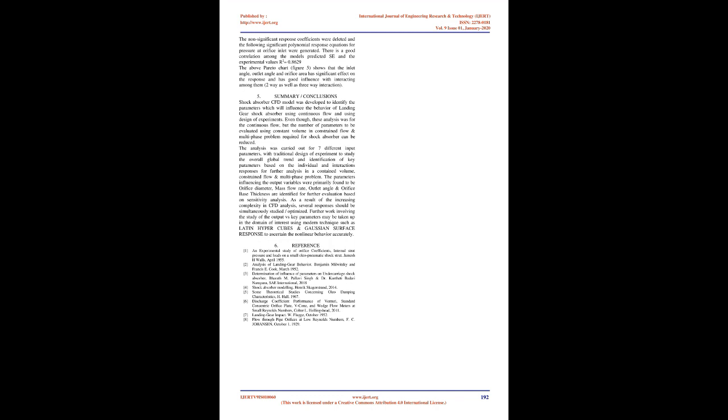The non-significant response coefficients were deleted and the following significant polynomial response equations were generated. There is a good correlation between the model's predicted values and the experimental values, R2 equals 0.8629. The above Pareto chart, Figure 5, shows that the inlet angle, outlet angle, and orifice area have a significant effect on the response and have good influence when interacting among them, in two-way as well as three-way interaction.